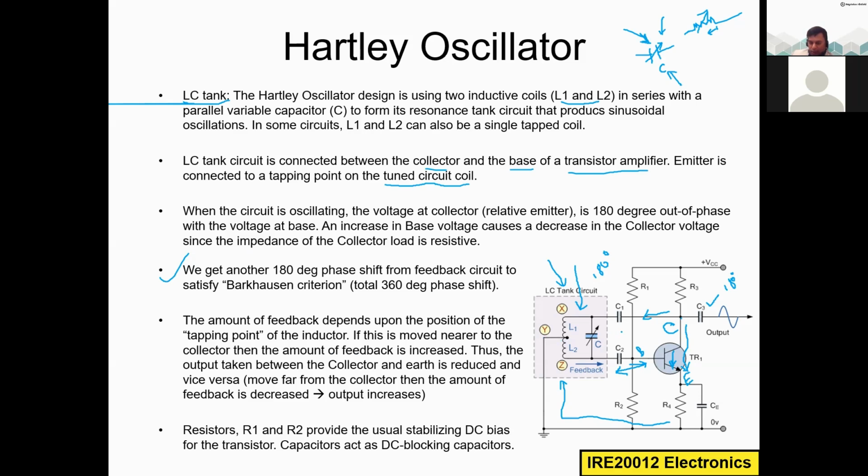So I told you I can change the base voltage. If I increase the base voltage, then what's happening? If I decrease the base voltage, then what will happen? If I decrease the base voltage, then this will be an open circuit, and the collector voltage will be high. This is just like a switch. You are giving this base voltage, and then you are making a connection or disconnection between these two terminals.